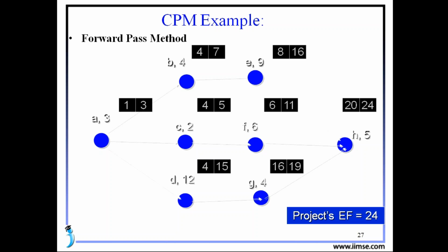After completing B only, we start our E. That means after the 7th, we start our E work. So the 8th. From 8 to 16, it's 9 days. E work duration is 9 days. 8 is the earliest start date and 16 is the earliest finish date.